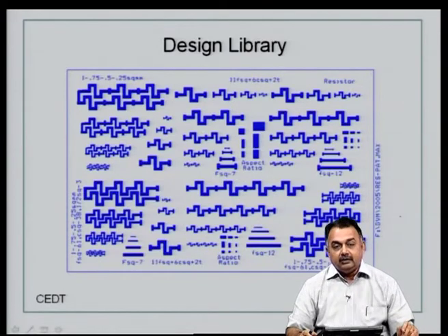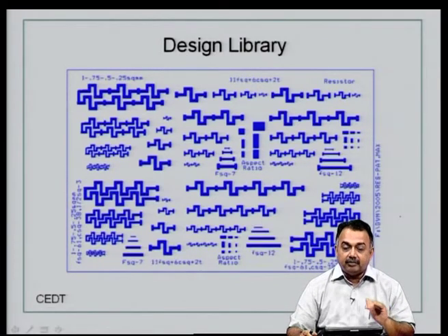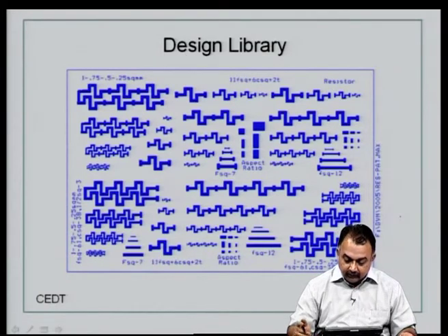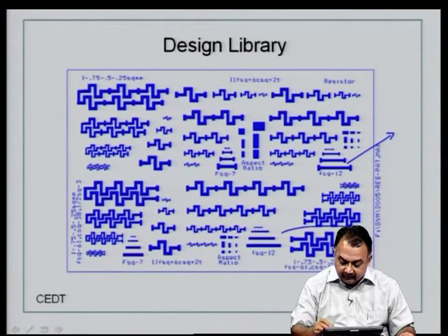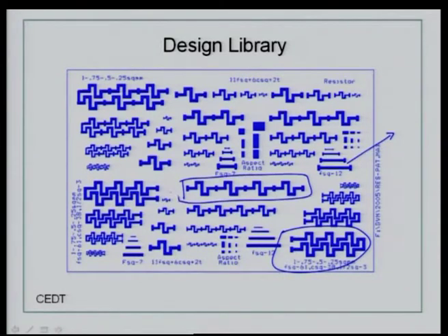Okay. So, again the key is using this pattern is fine, using the sheet resistivity and the same material is fine, but the process, whether it is screen printing or other forms that you will see shortly, is a key. So, you can see from very simple strips to meandering resistor patterns like this, and then here you can calculate the number of squares, and in between you have the copper. So, even if there is an error in processing in your bareboard testing, these will be shown up.